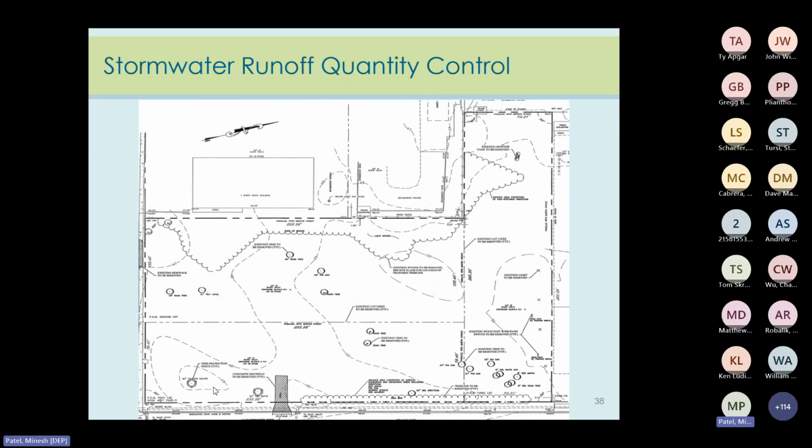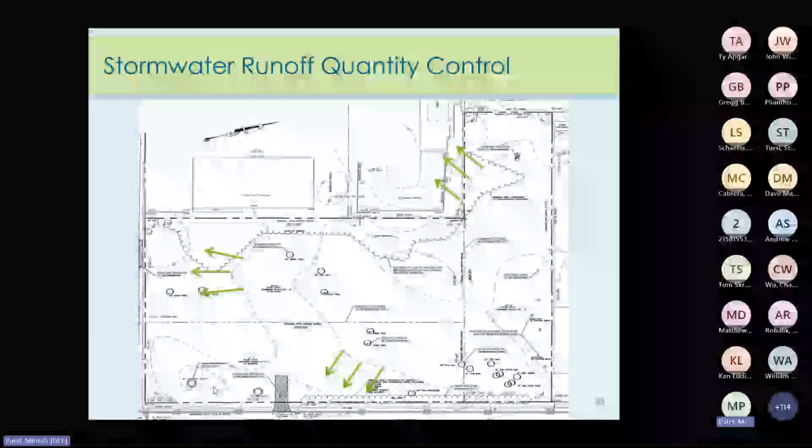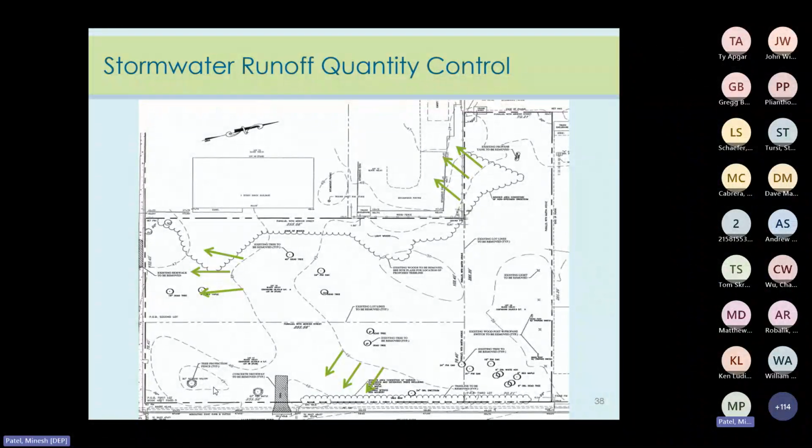So here is an example site. The flow was evaluated as sheet flow, directed primarily in a southerly direction. However, we received complaints of flooding along the road that is lying to the east of the project and from the area northwest of the project. It was determined that the drainage areas were not delineated correctly. Whether or not that was due to an incorrect evaluation of the topography, that's unknown. But this shows why it's important to properly evaluate the topography and delineate drainage areas.